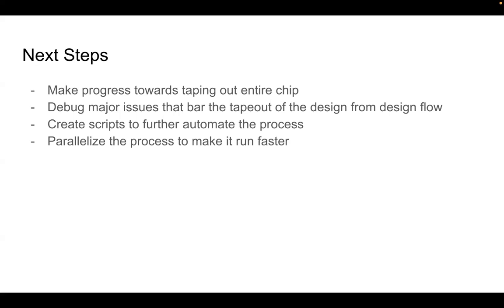In addition, we're creating scripts not only to automate the process as seen previously, but also to help with the setup of OpenLane itself and to set it up on ASIC Fab as well, the socket server that we use for all of our designs. That's one of the steps we're working on as well. Also, because the design flow of OpenLane is made of different modules, static timing analysis, layout, power analysis, that sort of stuff, if we can parallelize all those different analyses to make it run faster, we're also going to be working on that next semester.